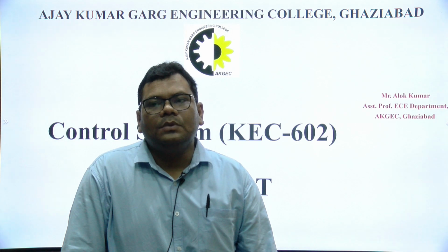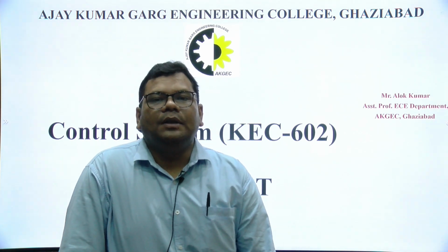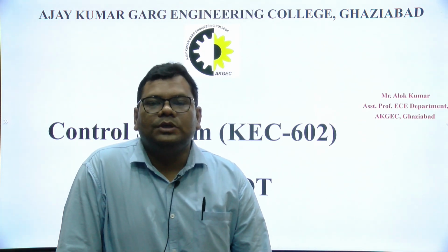We will do some examples. Then we will see how we can determine the stability using the polar plot. So this is the aim of this lecture. There are a few steps. First of all, the polar plot is the plot in which we plot the magnitude and angle with respect to the frequency. We will vary the frequency from 0 to infinity and plot the magnitude and angle. So this is the polar plot.